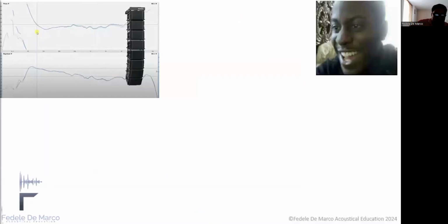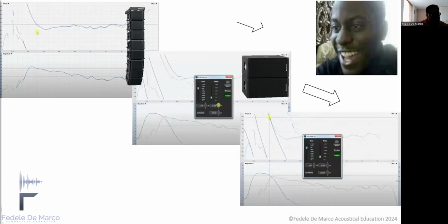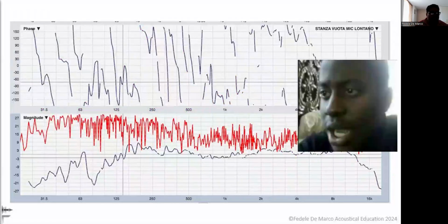We were trained for decades to turn on the main, the top, and continuously blast pink noise to find delay, to save the trace as reference, then to turn off the main, to turn on the sub, applying delay if necessary until the phase trace is aligned. Nice game if we were in an anechoic video game, but in reality all is more complex.